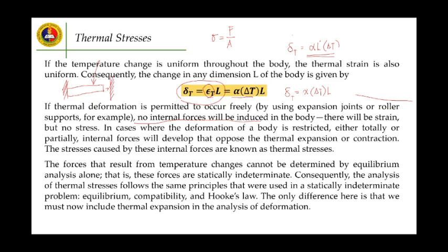And if there are internal forces involved already, stress will manifest. The forces that result from temperature changes cannot be determined by equilibrium analysis alone. That is, these forces are statically indeterminate.